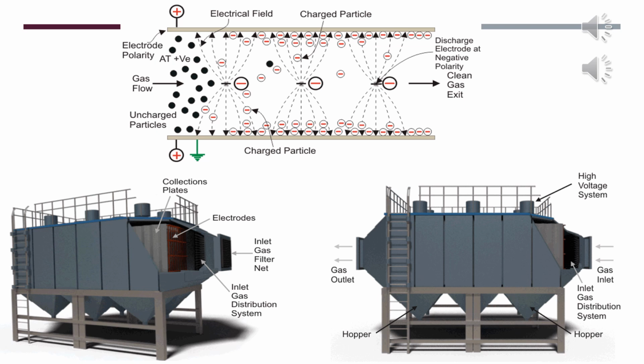The flue gases, after traveling through the electrostatic precipitator, become almost free from ash particles and ultimately get discharged to the atmosphere through the chimney. An electrostatic precipitator does not contribute directly to the production of electricity in the thermal power plant, but it helps to keep the atmosphere clean, which is quite important for living beings. Hoppers are fitted below the electrostatic precipitator chamber for collecting dust particles. Water spray may be used on the top to accelerate the removal of the dust from the collecting plates.